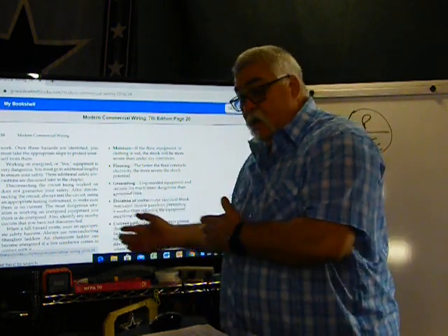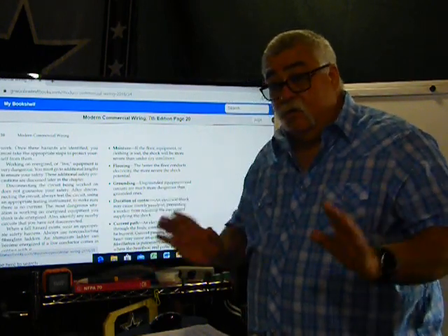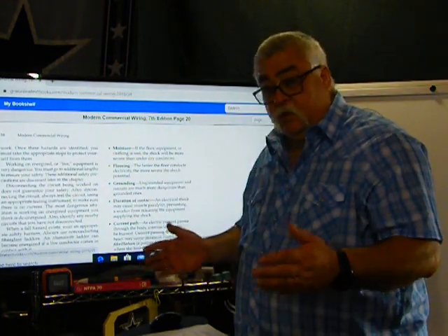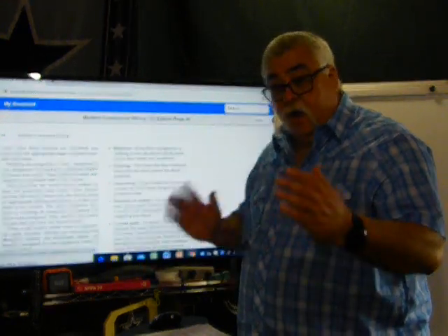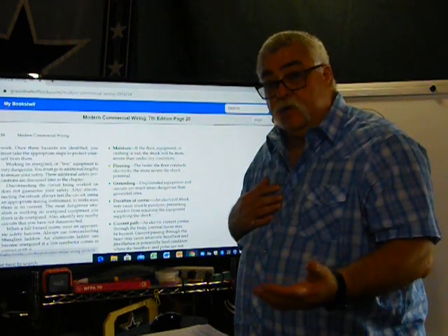A person that knows what they're working on and what it does. If I'm working on something that I have no clue about, I shouldn't work on it hot. But if I know how the machine works or whatever I'm working on operates, then I am a qualified person. Then I can work on it energized.